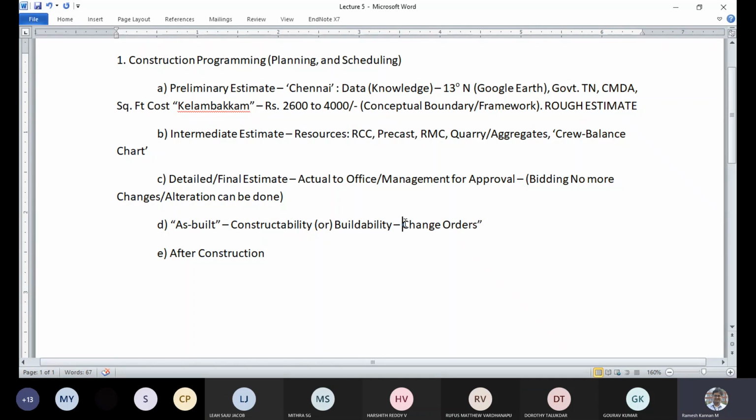If the variation is not much, contractors can have a change order. That's a clause in the contract. To protect themselves from becoming insolvent or vulnerable to the price change, contractors will generally ask for change orders. And in most cases the client agrees, because even if the client sues the contractor and hires another contractor, the price is going to be the same, right? So they cannot have a meaningful justification, right? That's why they are generally given a chance.